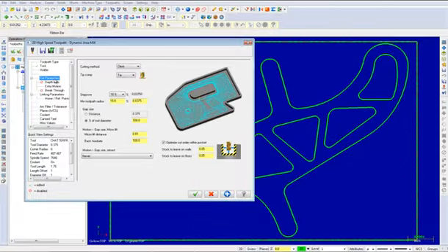This page allows you to enter values for different cutting parameters and compensation options for dynamic area milling toolpaths. Make all the necessary changes as shown. Ensure that the step-over percentage is 10. Also, make sure that the amount of stock to leave on the walls and floors is set to 0. And finally, change the percentage of tool diameter to 500.